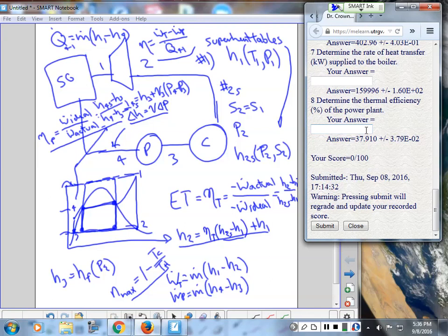So it wouldn't be a bad answer. What you would replace is delta H with Cp delta T, or C delta T, since for a liquid it's just C. So you'd ask, what's the specific heat of water? And then it could just be the temperature change. You could do that. I guess the problem is you get an approximate answer. This specific heat does change, depending on how much those irreversibilities raise the enthalpy versus the temperature. It's probably not going to change it much, so you're probably pretty safe doing that. But that's another way to do it.